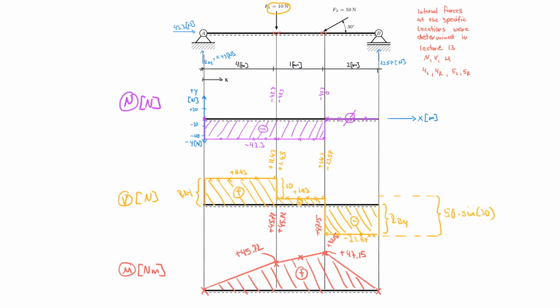Now I want to direct your eye to something very specific here, and maybe you've seen it already, and of course in the classroom I could ask you. Right now I cannot. It's a very teachable moment, so I love those in the classroom. But please go ahead and ask yourself if you see some relationship between the shear force diagram and the moment diagram. Look very carefully and think about what the relationship here is. I give you a few seconds and then I will, of course, tell you what it is. Yes, you are absolutely correct. There is a relationship, and the relationship is the shear force is the derivative of the moment.